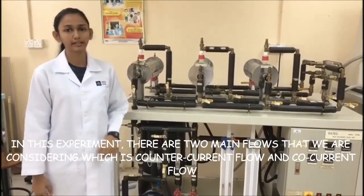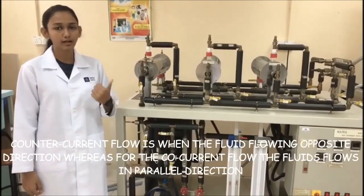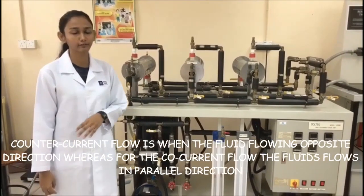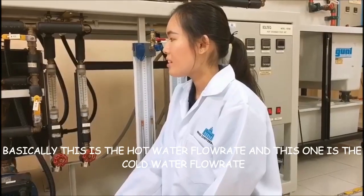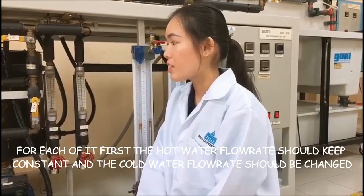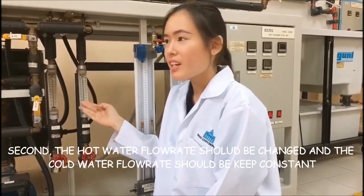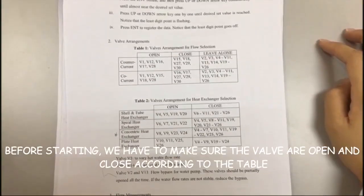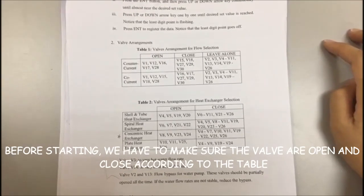In this experiment, there are two main flows that we are considering, which are countercurrent flow and co-current flow. Countercurrent flow is when the fluids flow in opposite directions, whereas for co-current flow, the fluids flow in a parallel direction. Basically, this is the hot water flow rate and this one is the cold water flow rate. For each of them, first, the hot water flow rate should be kept constant and the cold water flow rate should be changed. Second, the hot water flow rate should be changed and the cold water flow rate kept constant. So, before starting, we have to make sure the valves are open and closed according to the table.